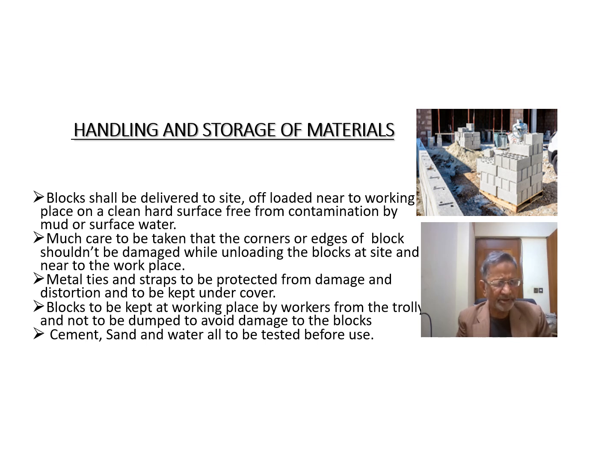Metal ties and straps are to be protected from damage and distortion and kept under cover. These metal ties and straps are used between the RCC columns and the masonry. Blocks are to be kept at the working place.